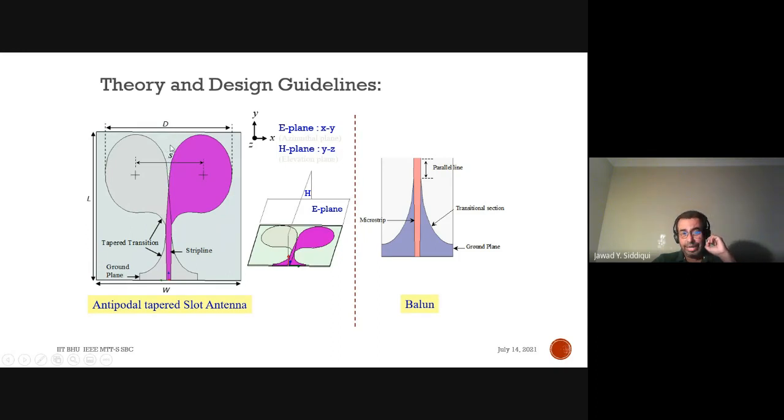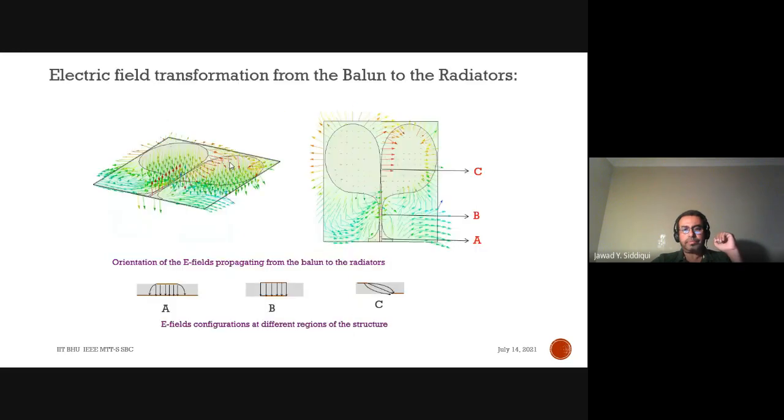I'm saying this because what we did is we used the split-ring resonator, placed strategically on this radiating line, in this space of the antenna, to filter the antenna, for filtering purposes, to weed out the undesired frequency. So first we have to understand how this antenna works.